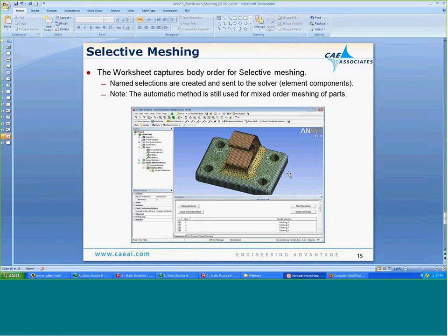What we can do is instruct the mesher that we want to mesh this base plate first, and then the outer ring, the hook, before we go ahead and create the tetrahedron elements. So this is the existing mesh that you've manually told workbench meshing to generate to influence the mesh that's going to be generated next. So very powerful tool here.